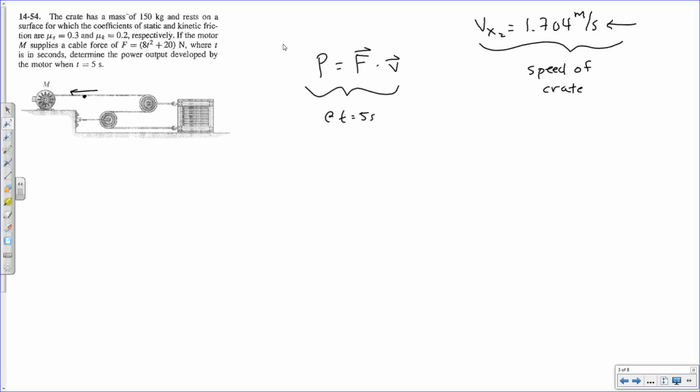And the speed at which it's pulling in the rope, well, in order to determine that, we need to use our dependent motion analysis. I'm going to have one datum, and I'm going to have one position vector that points to the right, call this S sub A, doesn't really matter, and then I'm going to have another position vector that points from the datum to some fixed location on the rope. Call this S sub M, if you'd like, for the motor itself.